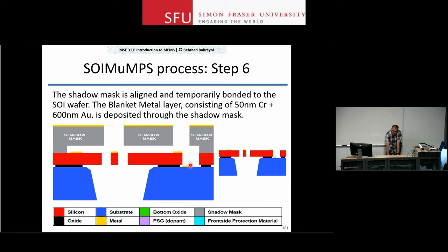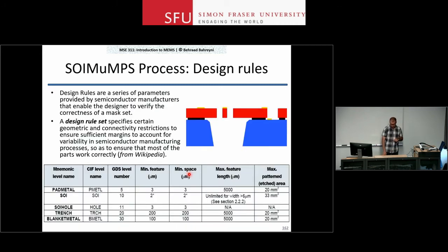And you cannot do that with the regular deposition, lithography and etch sequences we have because of the height difference here. Obviously, because you're using a shadow mask and none of those more advanced lithography techniques, your resolution is not that good, and it shows in the documentation for the process, but you now have electrical access to the handle wafer.